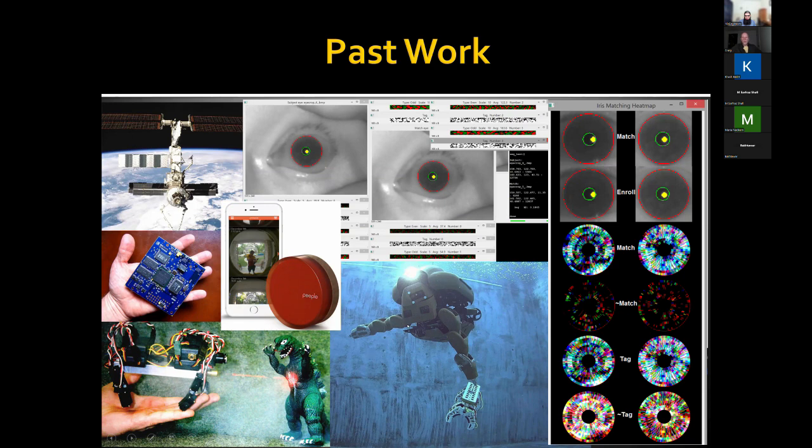Then this one that looks like it's in water here is a subsea robot I worked on in Houston. And I was working on the sensors on it. It has structured light, has a 3D camera at the top in the head there, and then a structured light sensor that uses a blue LED projector. And then the body opens. After it goes underwater, the body opens up and these arms come out and they can grab things. So it's used mainly for oil work.